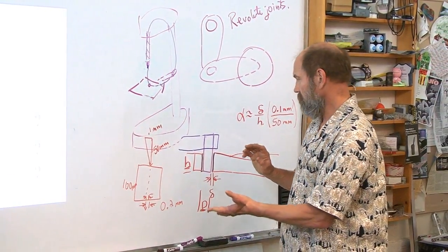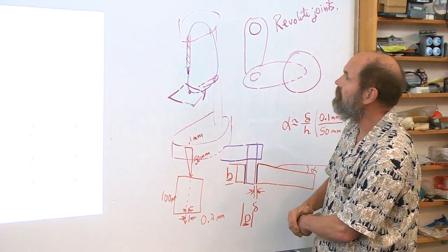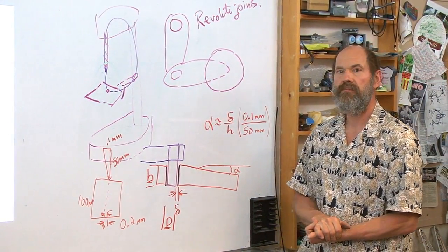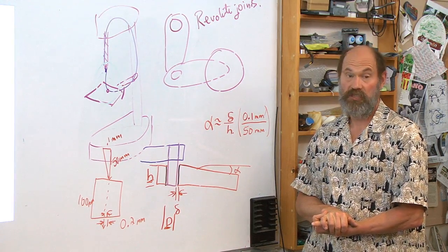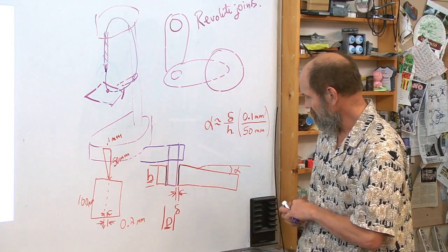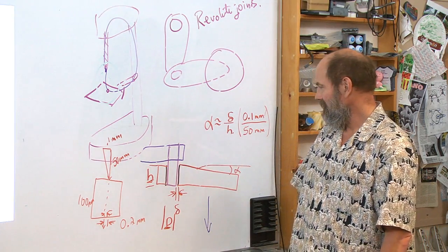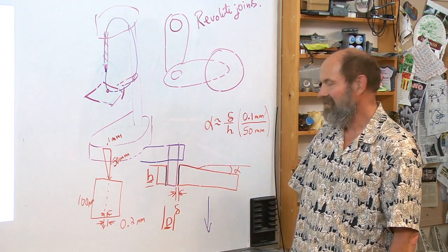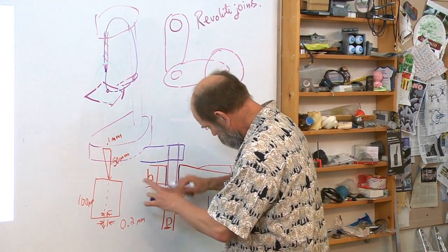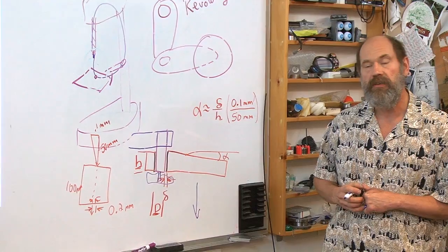What are the references? Where I got this out of the fundamentals notes, for example, or I've seen these kinds of clamping collars. What are the risks? What are the countermeasures? What's a risk in this design you see here? You're shy like me, I can tell. The risk is when I loosen this up to move this arm, there's this little thing called gravity, and whoom, this thing falls on the floor. Wow. That would be bad. I know. I can add another part here. There, I fixed it. That's the countermeasure. But that costs money. What's a better solution, maybe?